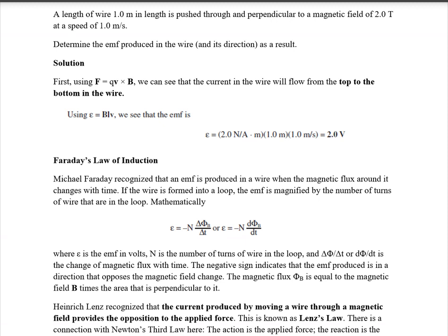The first one is Faraday's law. Faraday explains the magnitude of the induced EMF, and he expressed that the induced EMF is equal to N, the number of turns, times what? The derivative, or change in flux, over change in time. You must change d to delta. You learn this in grade 12 about derivatives in mathematics, but for the time being you must change this d to delta. Delta is change, therefore change in flux over change in time.